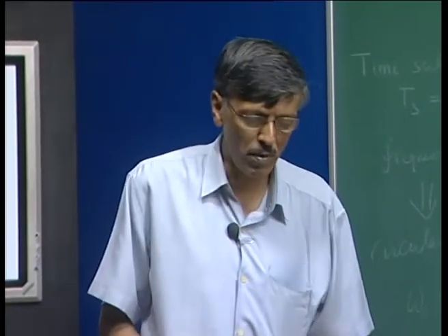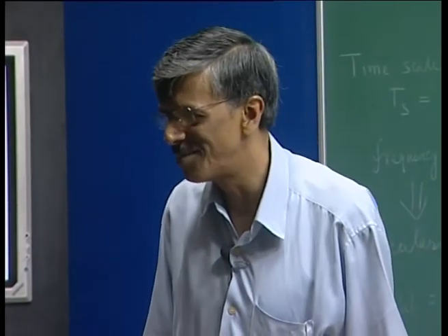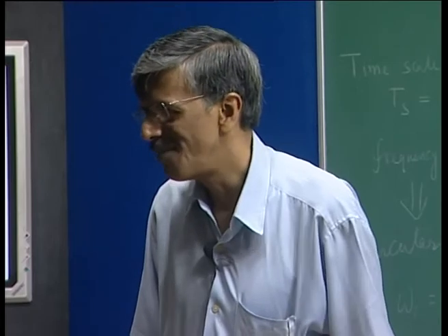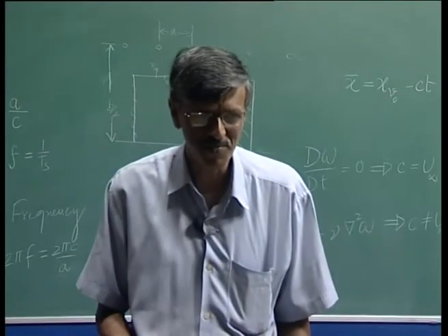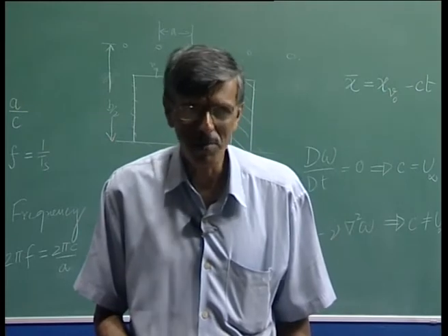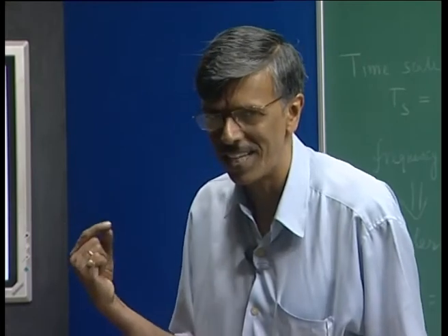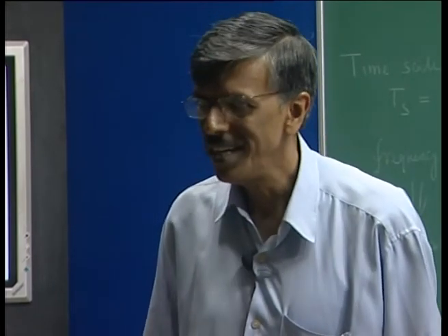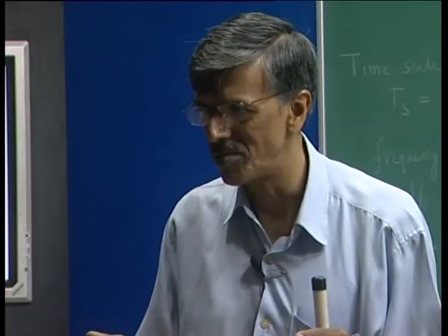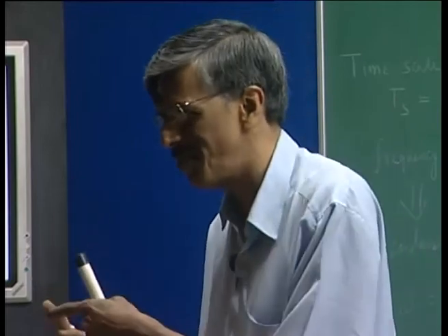Because of the prevalent mindset in the late 90s, we call this bypass transition. Why is it bypass transition? It is not really bypass, because you are still creating waves. But what you are creating is basically an assembly of waves. You have excitation at omega naught, 2 omega naught, 3 omega naught.